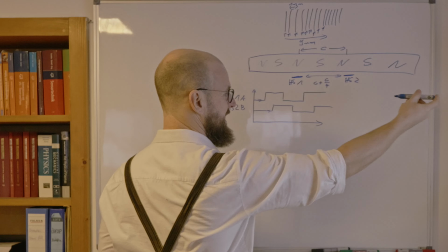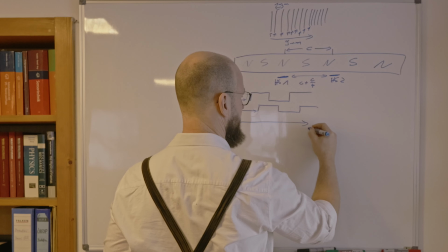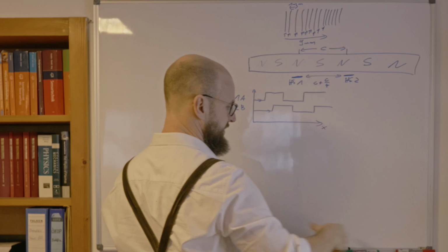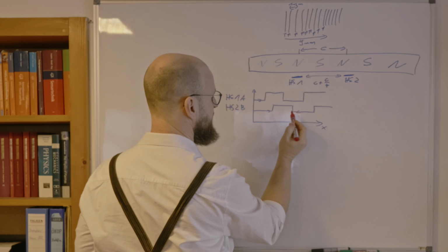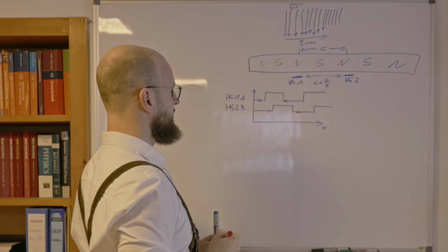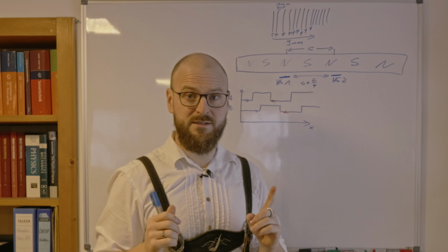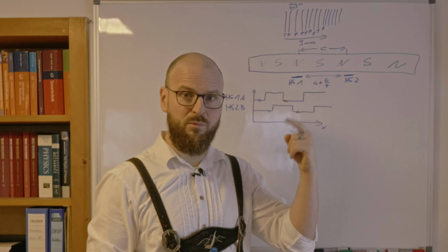But now going in the other direction, when that's the direction we are going, X, but now going from the other side, we see our sensor B would give us the first signal and then sensor A, the second signal. That means we need those two sensors to cope with one problem, and that problem is counting up or down.